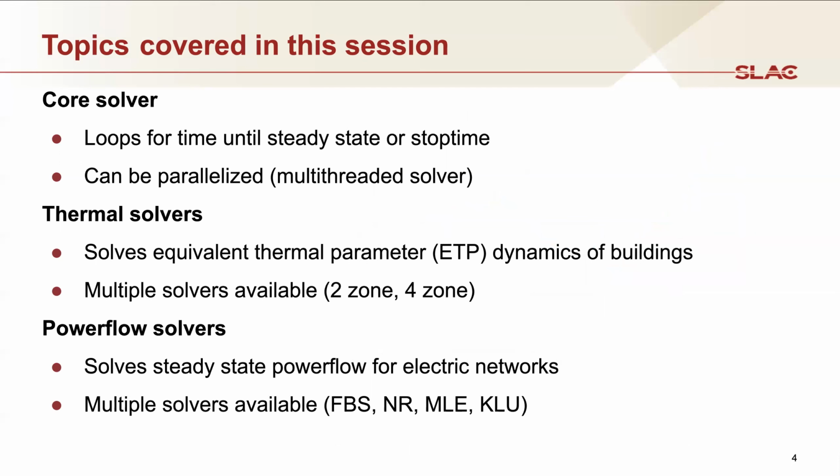so today's session, we're going to talk about how the solvers in Gridlab-D work. And there are three principal solvers used in the simulator. There's the core solver, which deals with the overall simulation itself. It's the solver that's responsible for advancing the clock and dispatching the other solvers that would be implemented in different modules. And so this core solver is running through the loop of each object, updating each object as the time advances. And so it's solving these objects for their steady state.